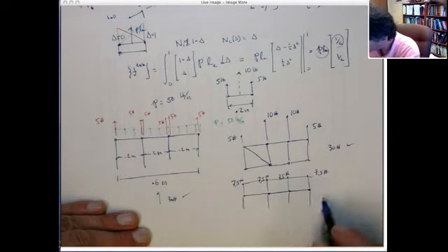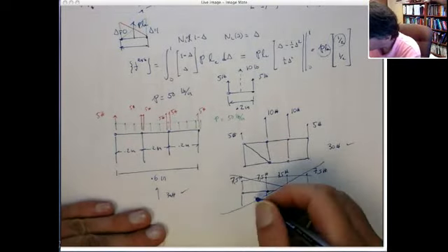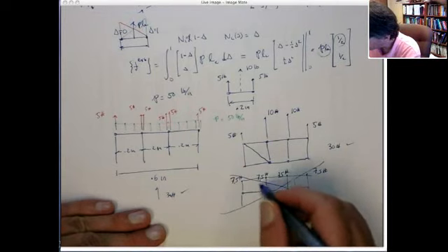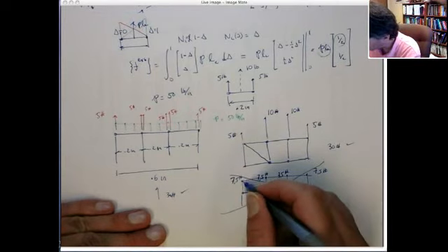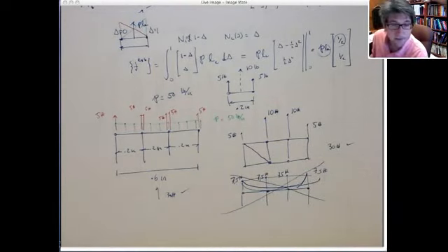Still adds up to 30, and they're all equal. That is incorrect, all right? What that is effectively doing is it's not uniformly distributed. What that's modeling is uniformly distributed here, the higher load, and then a little uptick at the end, okay? And so that's incorrect, all right?